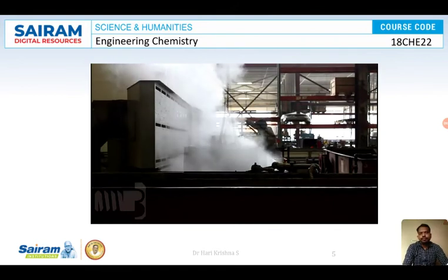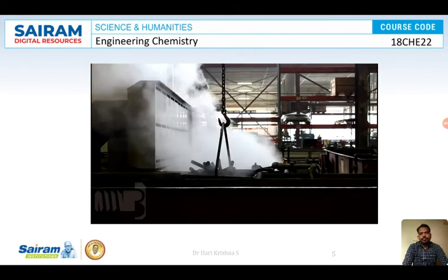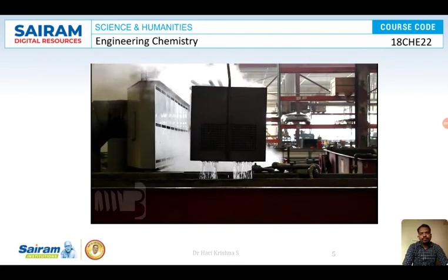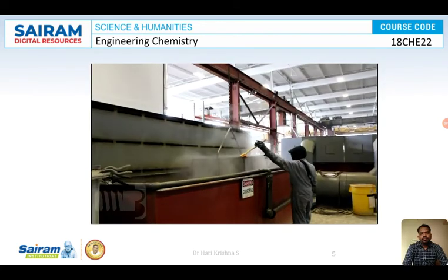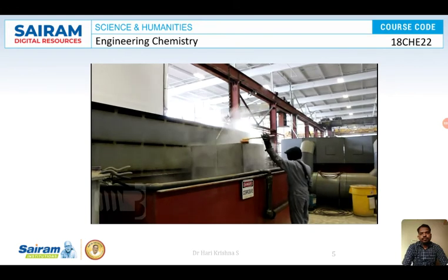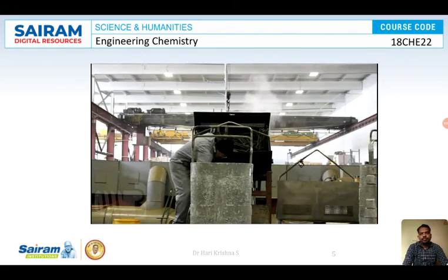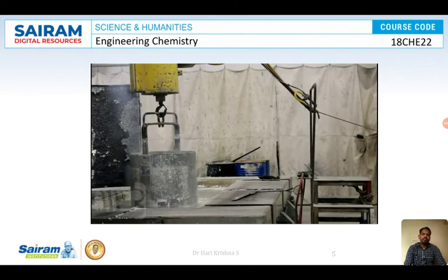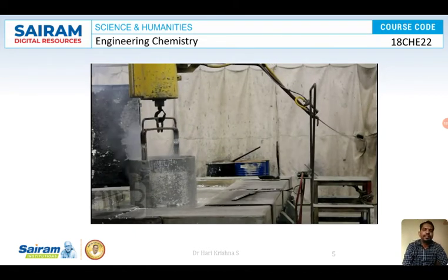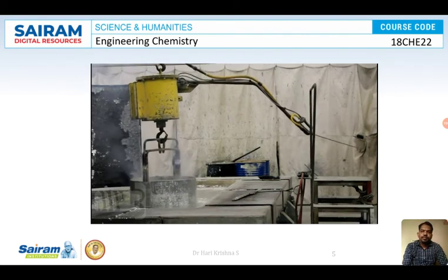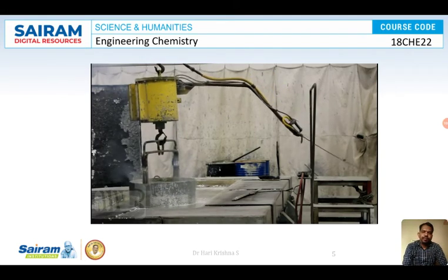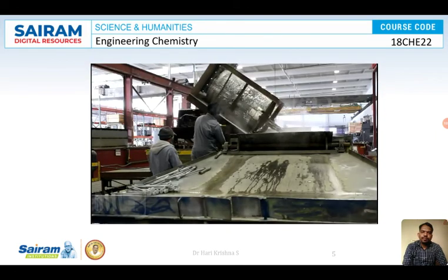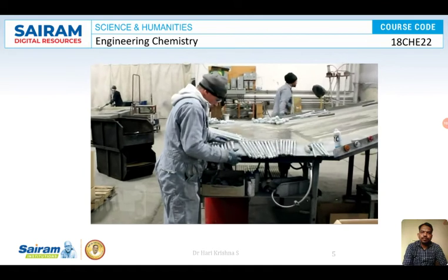They are then rinsed and submerged in sulfuric acid, which etches the steel so the zinc can penetrate the surface. The bolts are rinsed again, then submerged in flux to facilitate the bond between the zinc and the steel. The bolts are then transferred to baskets or racks and submerged in 840-degree molten zinc for 2 to 5 minutes, depending on their size and grade. The bolts are removed from the zinc and rapidly spun. Centrifugal force removes excess zinc from the threads. The bolts are cooled in water tanks, inspected, and packaged for shipment.